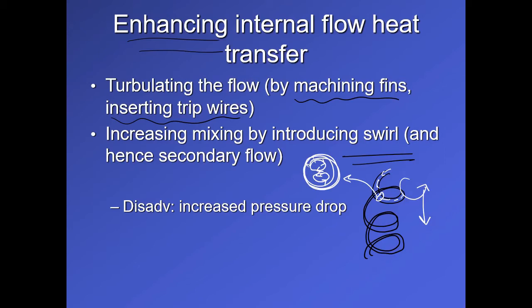Okay, but the disadvantage of these approaches is that all of them result in an increased pressure drop. So that adds to the cost, because increased pressure drop means that you have to apply more power to allow the fluid to flow in the pipes.